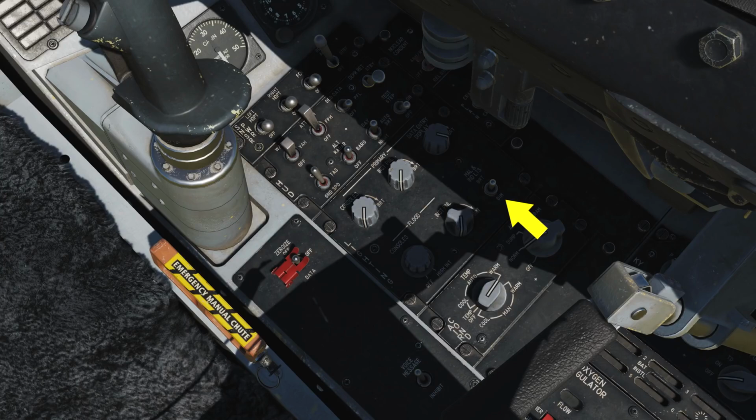The malfunction indicator light switch sets the AOA indexer, nose wheel steering, and air refueling lights, the DED, ECM control panel, MFDs, and PFLD, as well as the threat warning systems to either dim or bright. The flood instrument knob controls floodlight intensity on the instrument panel, and the flood console knob controls floodlight intensity on the left and right consoles.